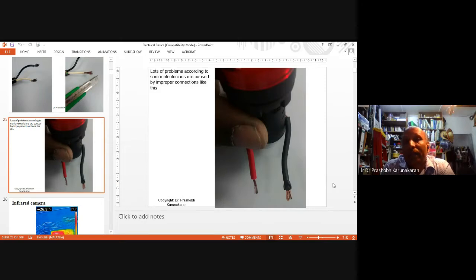And the examiner would look for copper. If you show a bit of copper, minus 2 marks, minus 2, minus 2, until you can fail, because there is a lot of wiring you have to do during your practical exam. So that's why the technicians in Sarawak strip very little, and because they strip little, they tend to screw on the plastic. I've seen so many cases, myself also during my projects, and the senior guys told me all over Sarawak, the number one problem is this one.